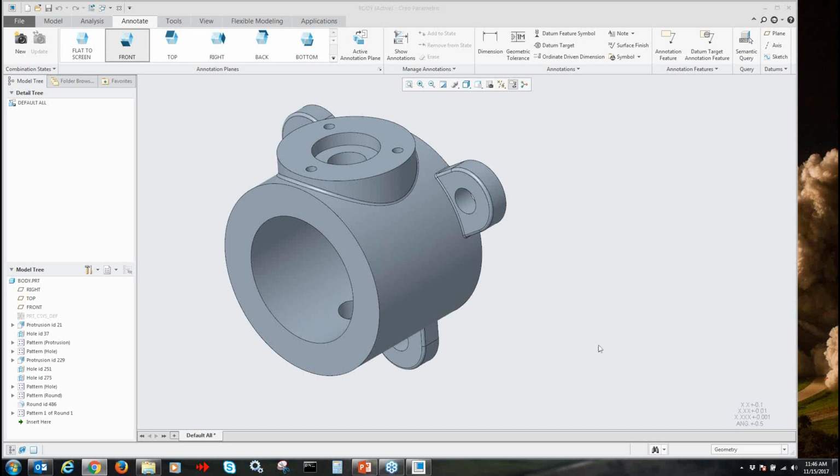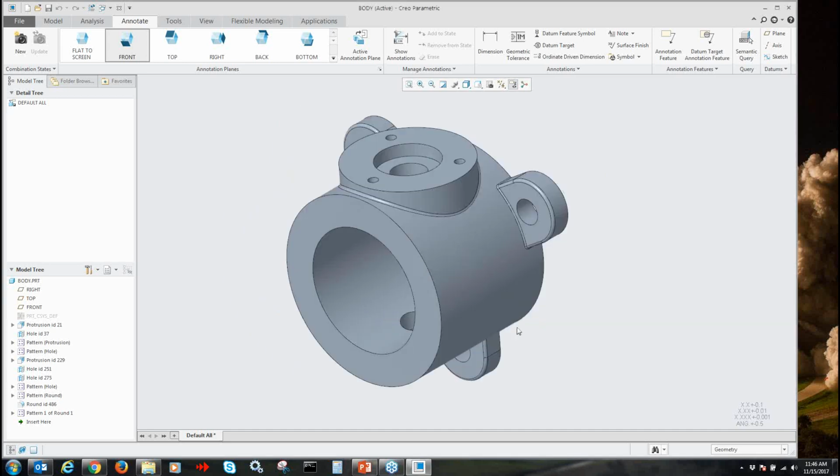One little key note here I want to make you aware of. If you're building out your general views and you do select that no option there, you don't have an option to go back. If you create a combination state view, you have to start the drawing all over. That's one of the areas that I found is a little weak on how it handles those issues with those files. Once I set that to no, I don't have the ability to switch back and modify any of those combined view states.